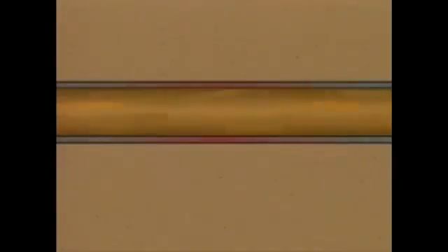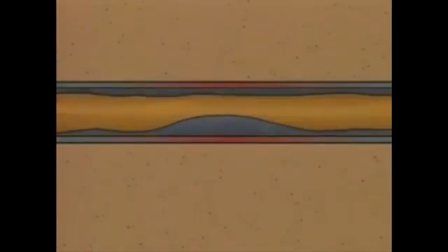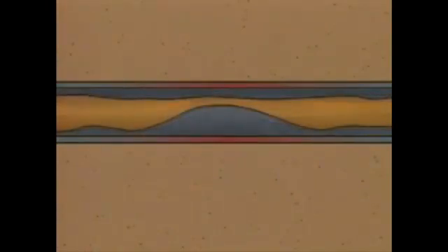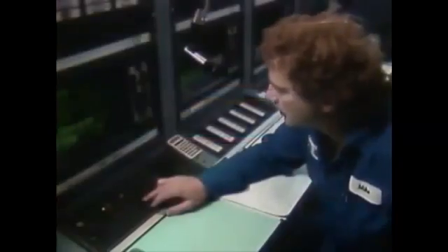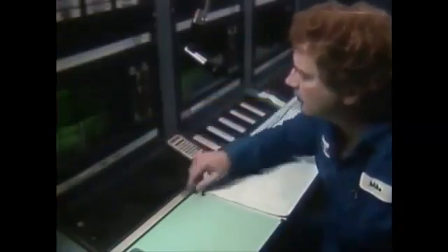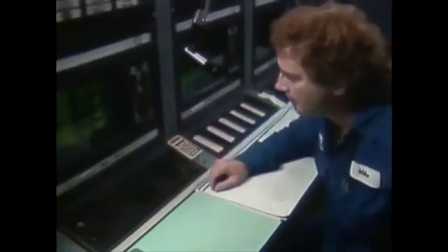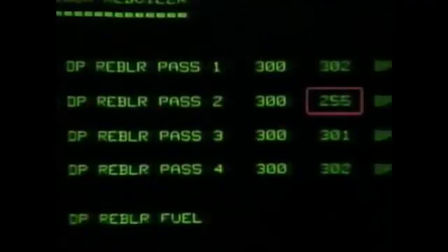A hot spot may lead to coking, the buildup of carbon deposits inside the tubes. Coking can restrict fluid flow and cause heat transfer problems. Coking may be detected in multipass furnaces by comparing the flow rates through the passes. The flow rate will often be lower than normal through the restricted pass.